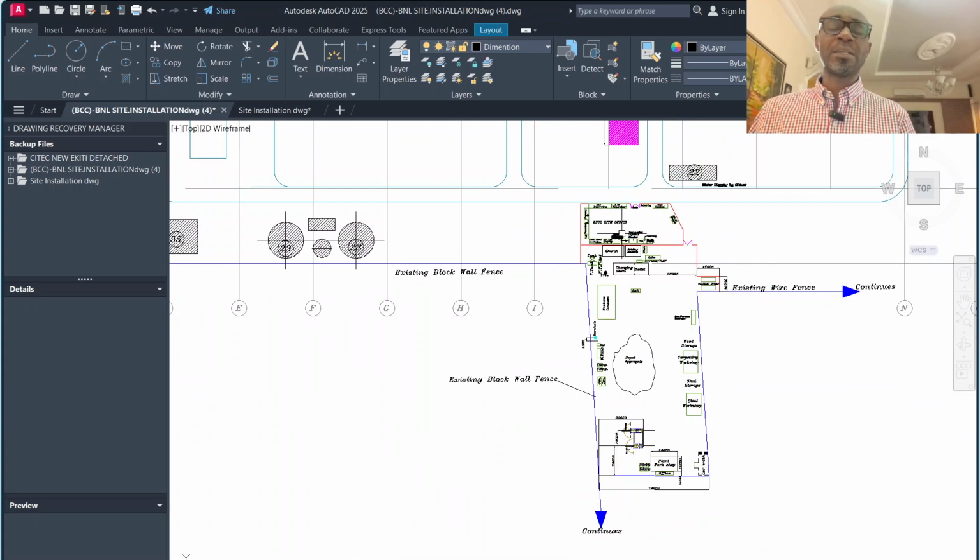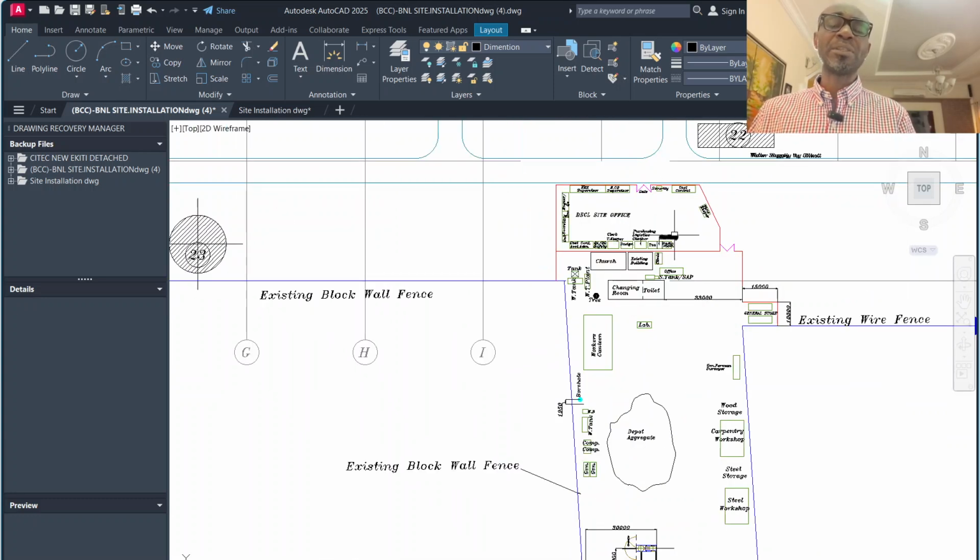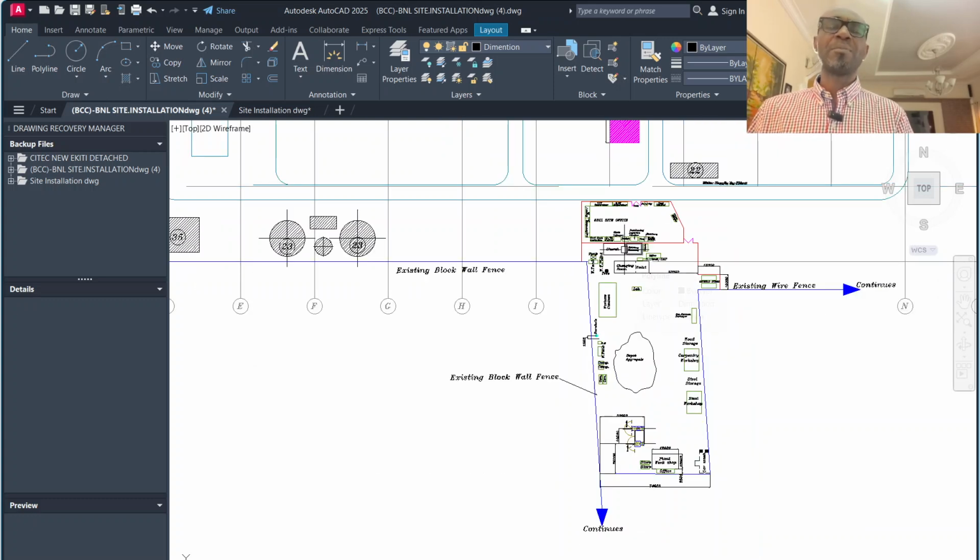You know that I did say what determines how many you will provide for is the volume of earth you need to excavate. So that will be determined by the number of months you have earmarked to excavate the whole of the volume in the bill. So that will give you the trucks and the excavator, probably as well the compactor.